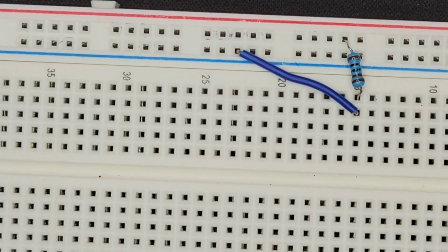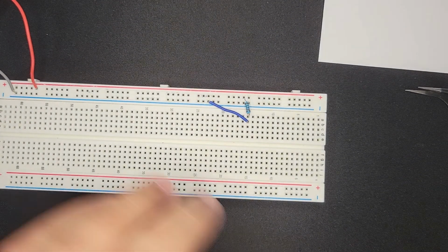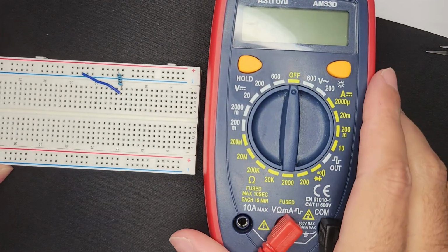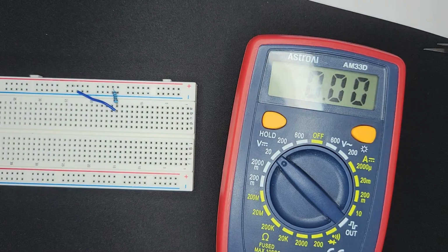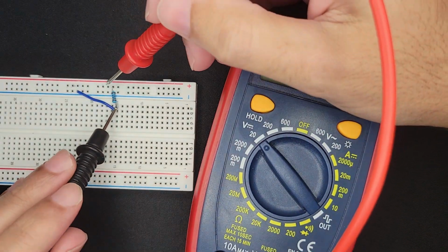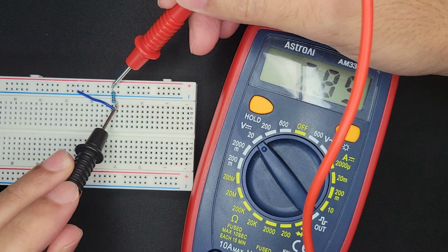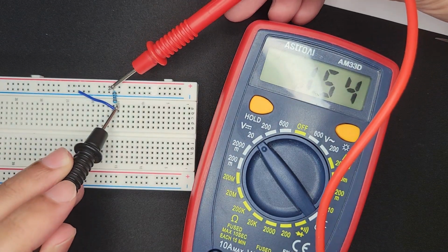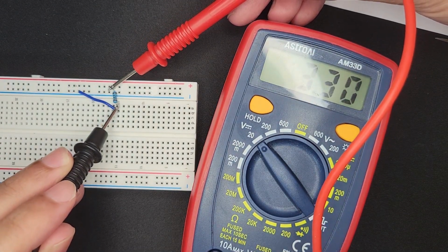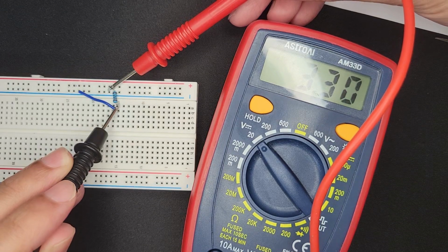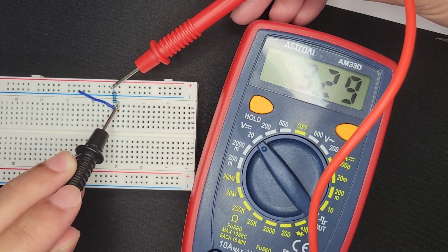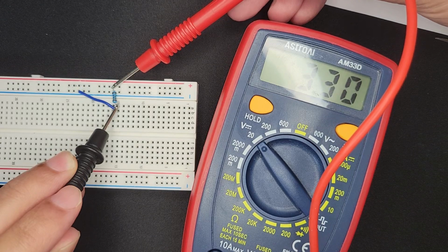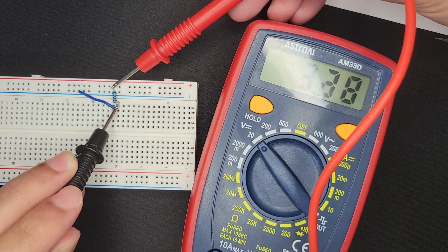So what we have to do is use our meter. Get this little guy, make sure he fits on the screen. And if we measure the voltage, let's put our positive probe to the side. That's positive. Can you see that there? I know the wire's in the way. So it says 3.3 volts. So right now we're reading voltage and not current, because voltage is easier to read than current. But what we'll do is we'll break this open and see the current flowing.